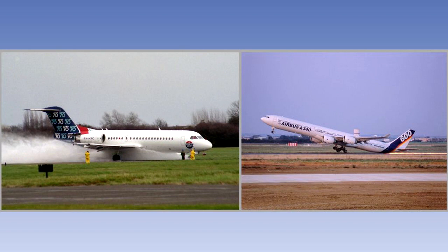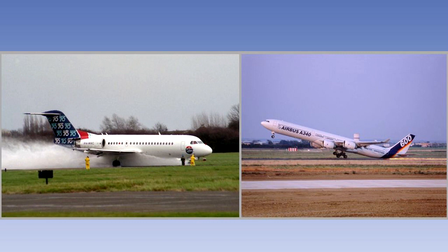Earlier on in the lesson, we mentioned the rigorous testing that aeroplanes go through before they are issued with an airworthiness certificate. A large part of these tests involve discovering the aeroplane's performance capabilities. These include finding out its average takeoff distance, landing distance, climb gradient, range, and so on, under a variety of different weights and environmental conditions, with a brand new aeroplane flown by a highly skilled test pilot. These particular performance figures gained by the manufacturer under strict test conditions are described as measured performance.